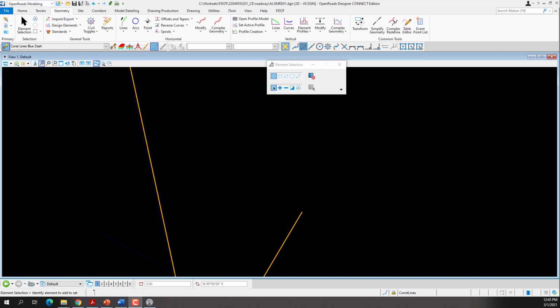So for construction line 4, the first step is to click on the existing state road. We want to try and get this bearing. If you click on it, you'll notice you can't select it. The trick is to select the element, which is the existing State Road 61, and then right click, because right now it's read only.